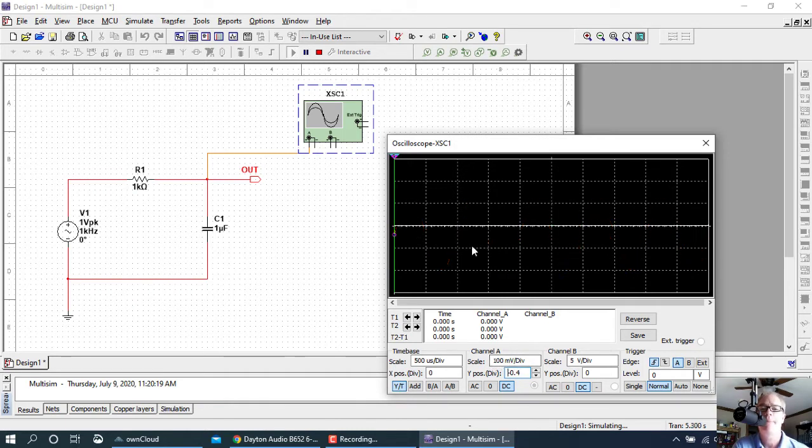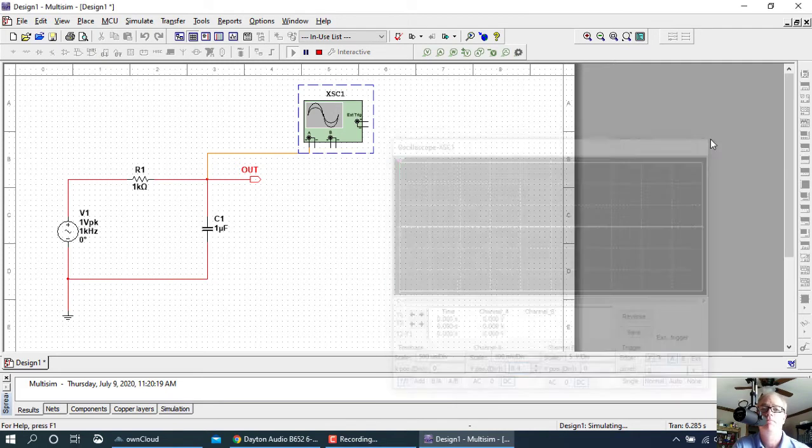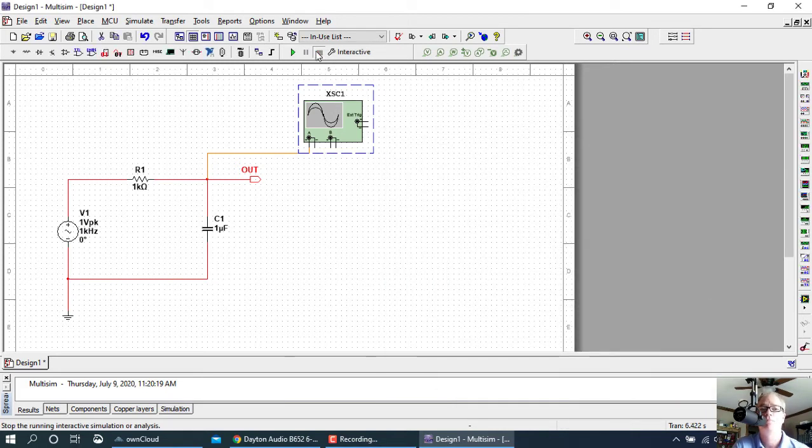So we're looking at about 300 millivolts, a little bit more, 310 maybe, 310 millivolts peak to peak, from the positive peak to the negative peak. And I've measured that manually using the grid on the screen. That's quite a bit less than what we started with, because peak to peak we started with 2 volts. Okay, enough of that. That was review.